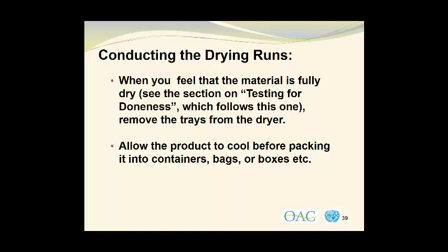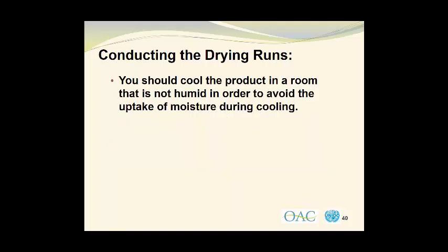You should allow the product to cool before packing it into containers, bags, or boxes, and this is because the warm material will often sweat and lose just a little bit of moisture that might be going into the bag, and that can promote microbial growth if it is trapped inside the container.